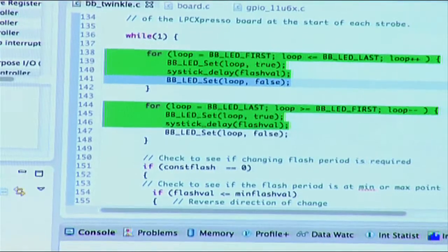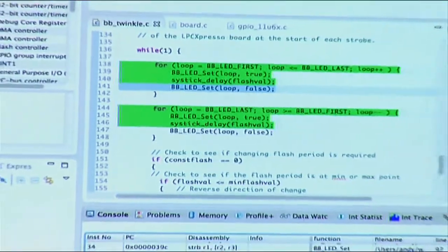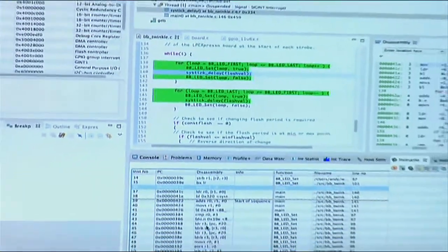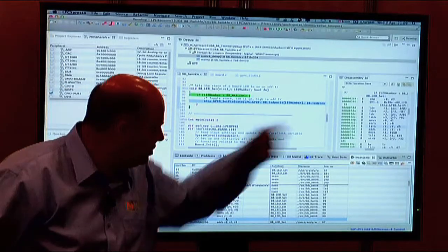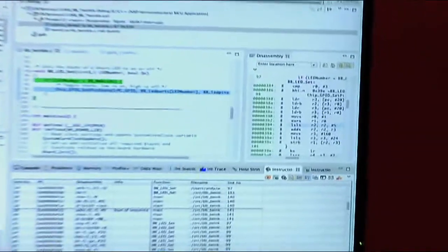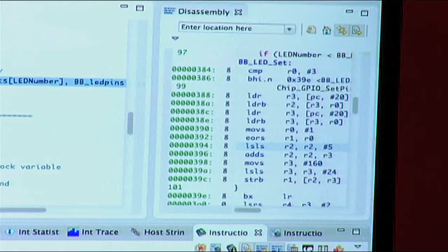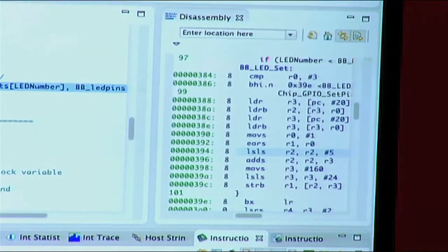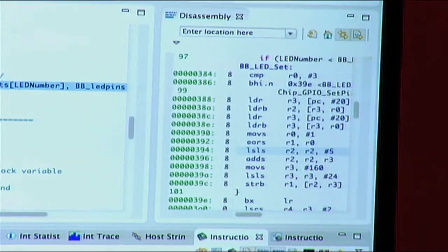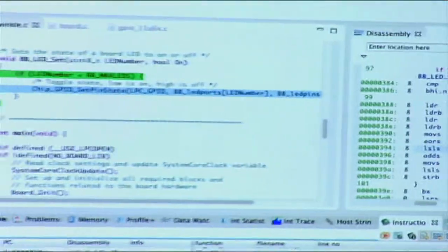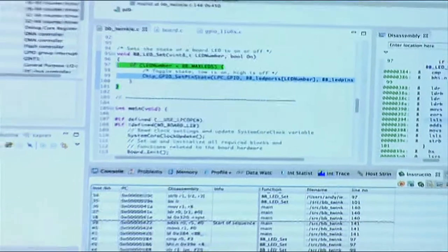And again, that disassembly view will update as I select different instructions, as you can see on the right-hand side of the screen. This enables you to tie your trace collection up to your source code and an actual physical disassembly of your source code, and link it to your trace buffer.